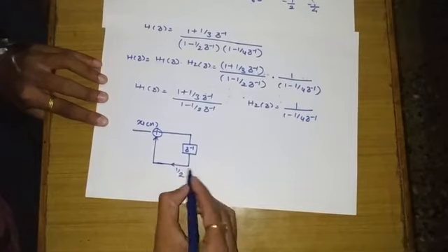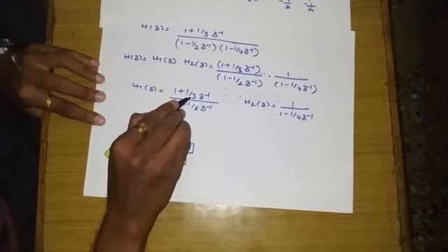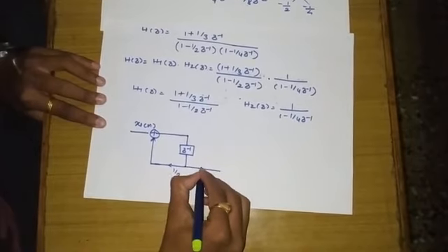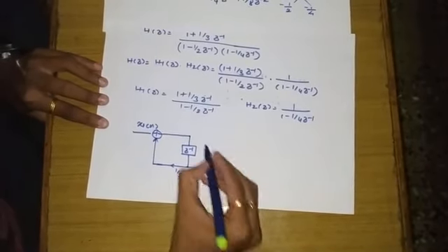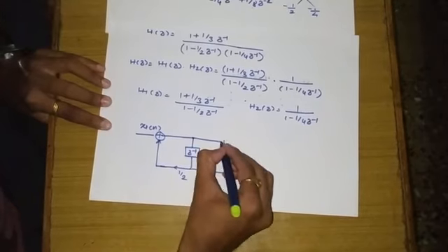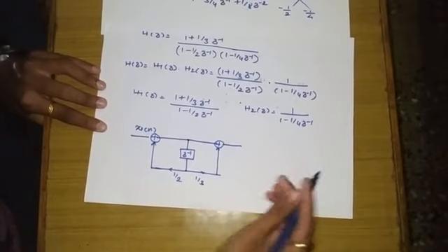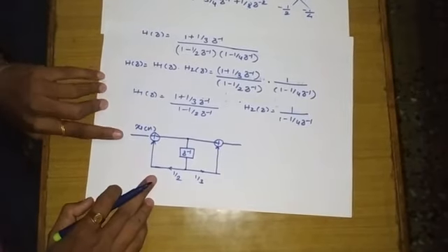This is for the all pole system. Now coming to the all zero part, again we need 1 by 3 here. So this is multiplied with 1 by 3 and one adder, so we'll add this plus here. Let this be our first transfer function realization.